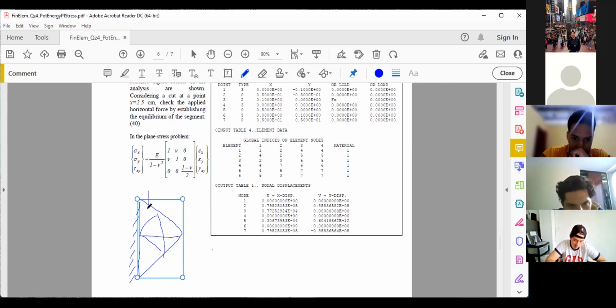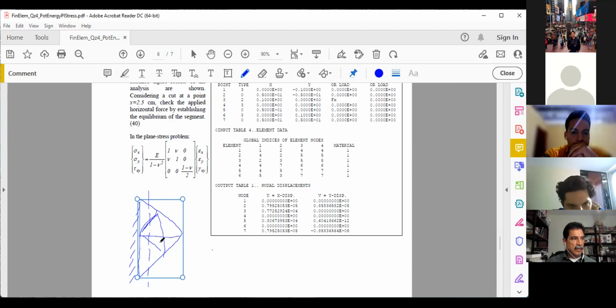So we need to do a stress calculation in this cut. By symmetry, that's what Mr. Nevares said, this part here supports the same stresses as this region here. So the stress in this triangle is the same as this one. The strain in this triangle is the same as this one. So we need to calculate the stress only in these two triangular elements, here and here. Now, to get there, I need to calculate epsilon x. That was the question.